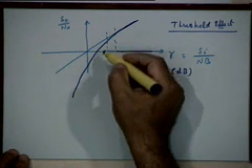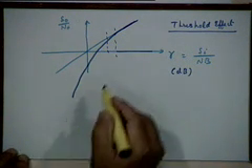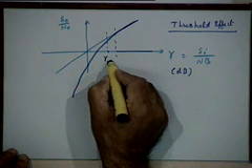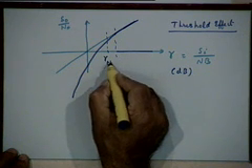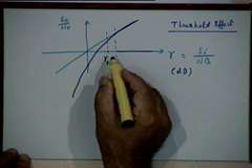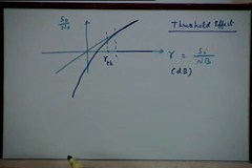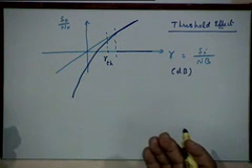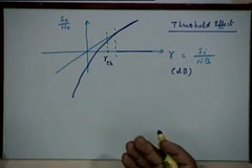So it degrades much more, and therefore there is a concept of a threshold value of the input SNR, and you must operate always above the threshold value. Because if your receiver operates below the threshold value, rest assured that you will get a very bad, highly mutilated output, which will not resemble the signal at all.